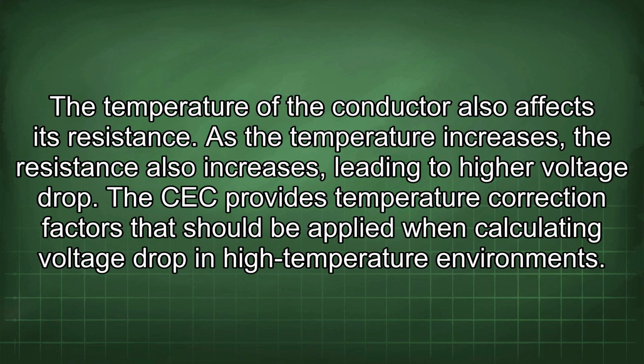Secondly, conductor temperature. The temperature of the conductor also affects its resistance. As the temperature increases, the resistance also increases, leading to higher voltage drop. The CEC provides temperature correction factors that should be applied when calculating voltage drop in high-temperature environments.